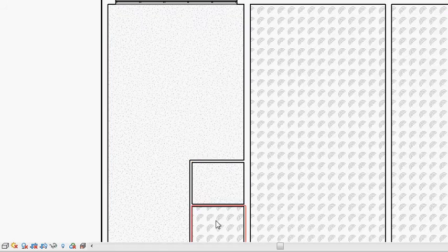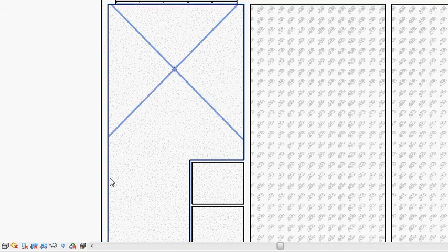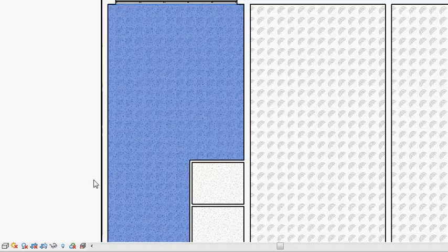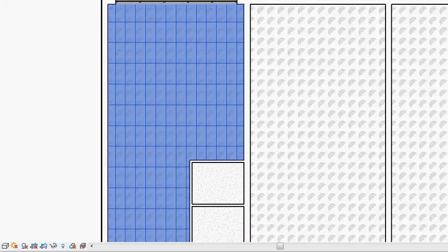And then the tab key lets you cycle through and select additional items within Revit that are hard to select. Tab and shift tab lets you cycle backwards. So there's my grid and my joist. Got my spaces in there. It probably eliminated the space inside these two rooms, so these two would be calculated as two different rooms and spaces, where this would be one.